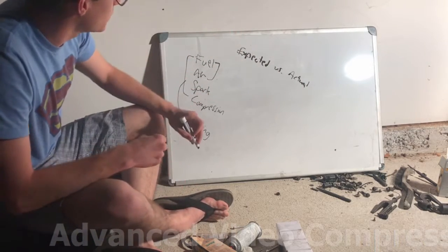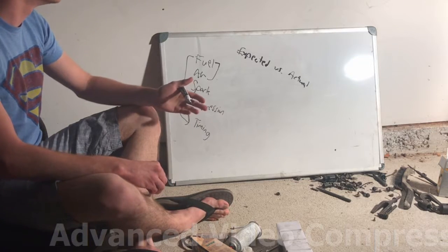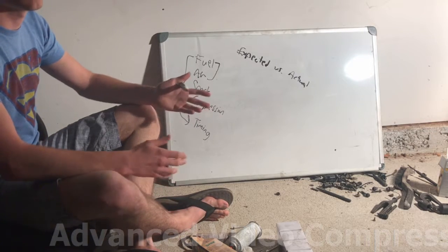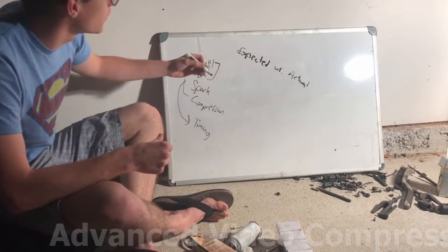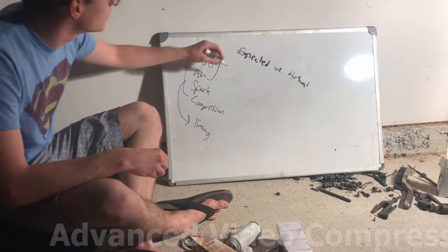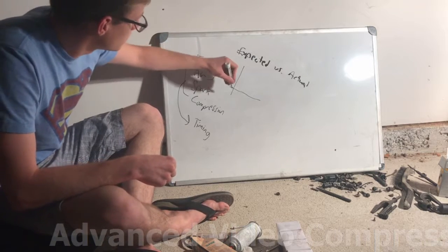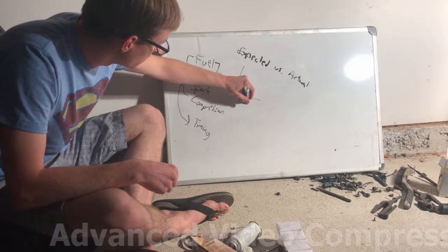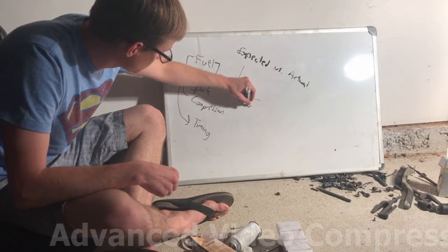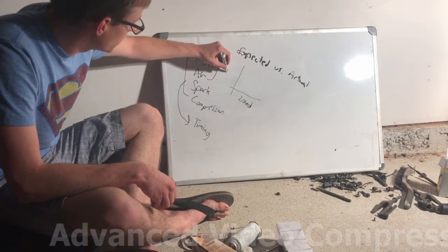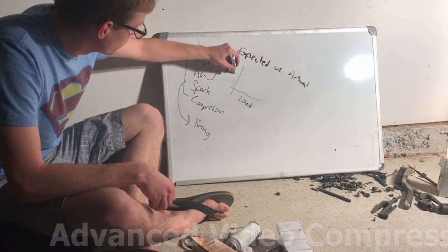So any car is going to have an expected table of MAF or MAP sensor values, and I like to call this the MAP table. So this table is basically going to show load, engine load, versus RPM at any given point in time.